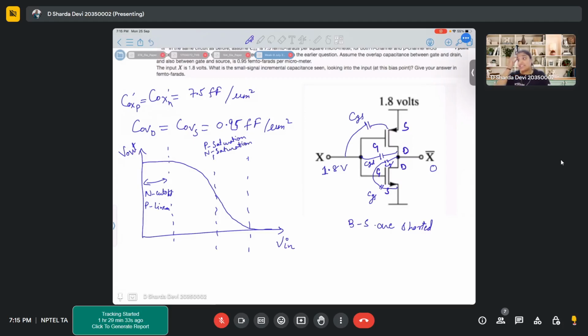That is where the same equal currents flow through both the transistors. Now, in this region, which is beyond, when you give 1.8 volts to your input, your P actually goes to cutoff, because if you observe very carefully, your VSG is 0. So the moment your VSG is 0, that means your transistor is off, right? And your VD is 1.8 volts.